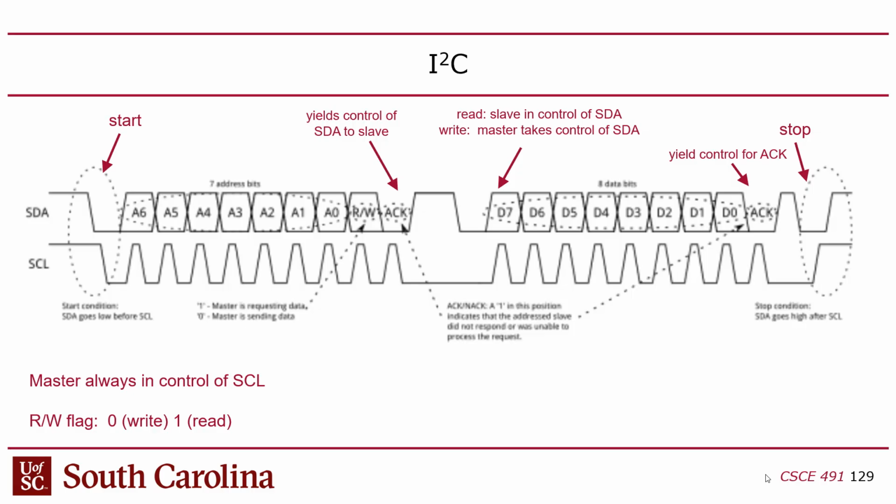And you want to keep it high long enough for the latch to work. Make sense? And again, on FPGAs, you can do this. It's just, generally speaking, you avoid latches. This is one case where you deliberately use a latch. Make sense?